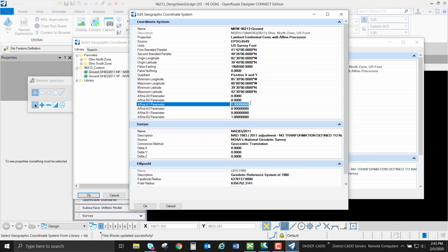This scales our northing and easting by the scale factor that we already have. The scale factor would be calculated using your survey software like Trimble Business Center, Leica Infinity, or the Survey Master spreadsheet, using the Create Scale Factor tab inside there.